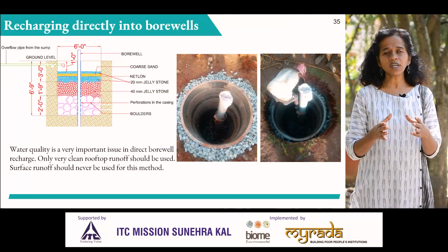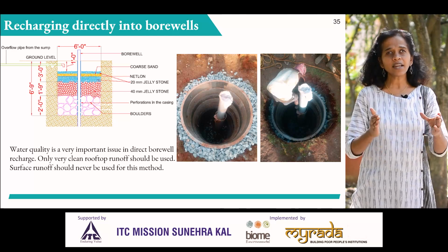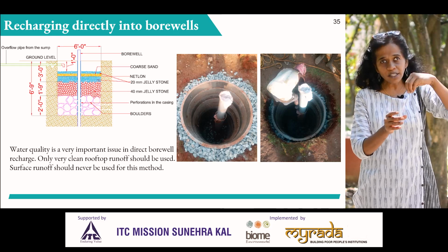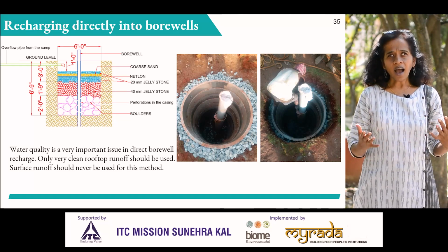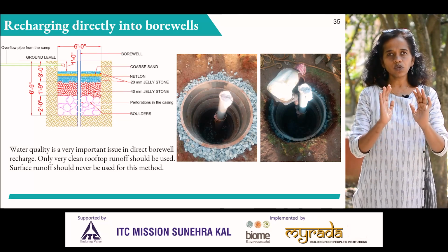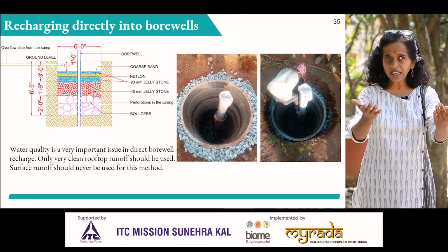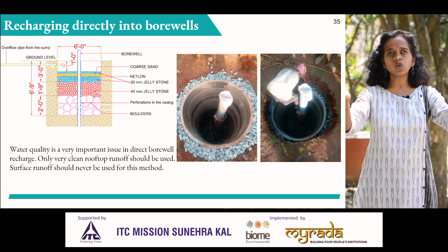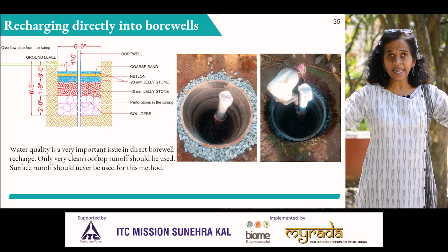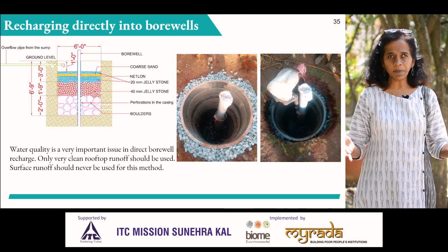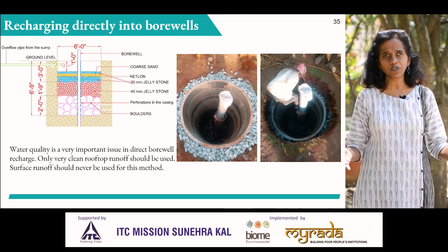You can also look at a strategy of direct borewell recharge. Here we are trying to put the water into the borewell directly. How do we do this? So you normally dig a pit around the borewell. It's like a recharge well. So it could be 3, 4, 5, 10 feet in diameter based on the space available. You need not go very deep. 8 to 10 feet of depth should be sufficient.